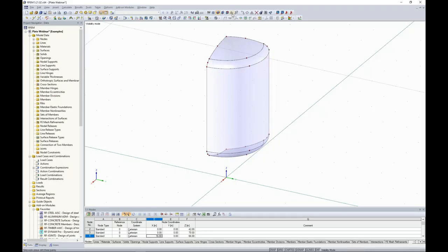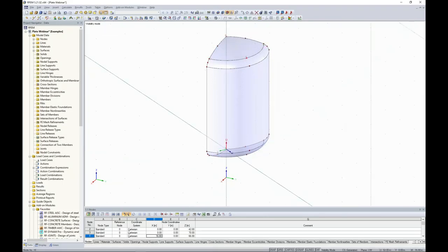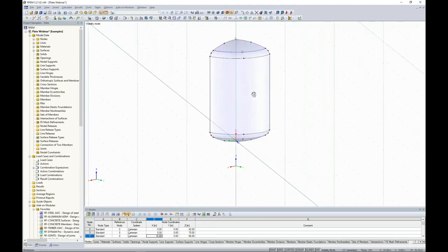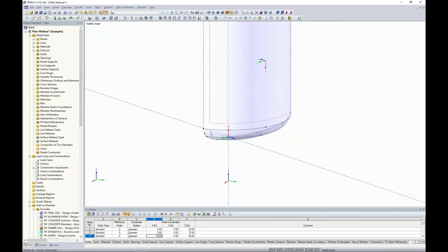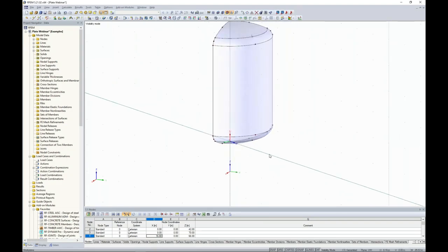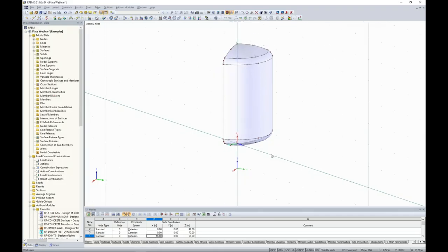And it's very quick to do by selecting this tool up at the top, where we can choose a work plane with 3 points. So I'm going to choose my lower center point, my upper center point, and my third point is going to be on the outer center. Now you'll notice I've created my own user-defined coordinate system based on UVW axes here, and this will be extremely beneficial, which you'll see as we begin to model.